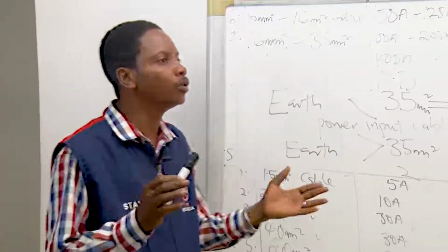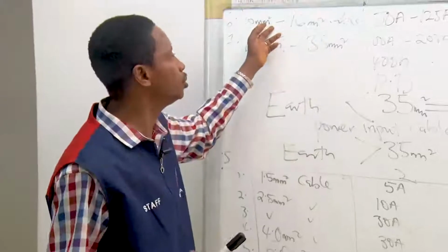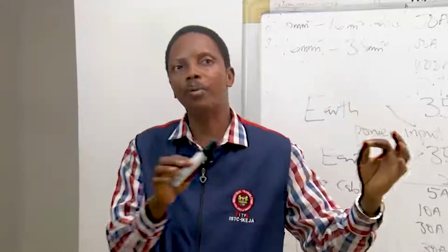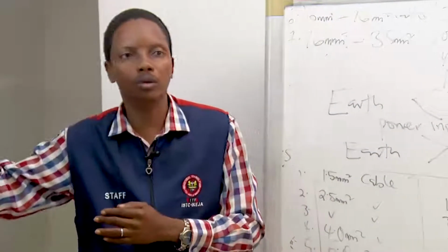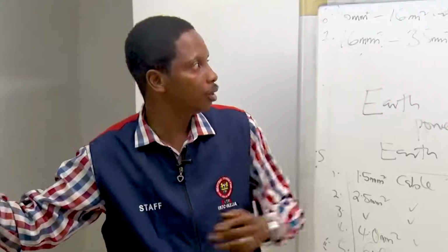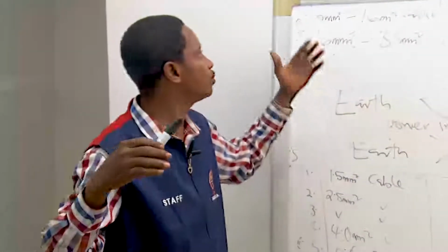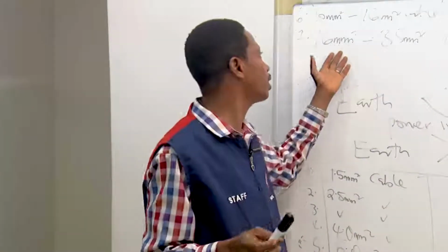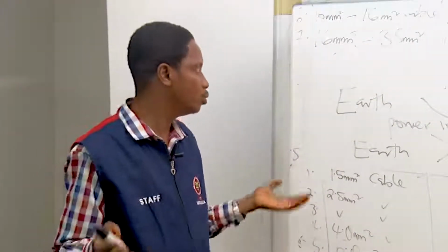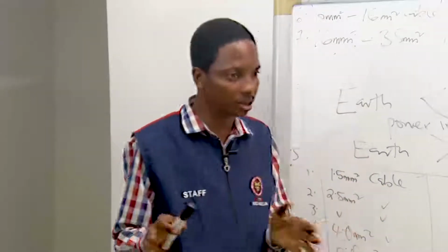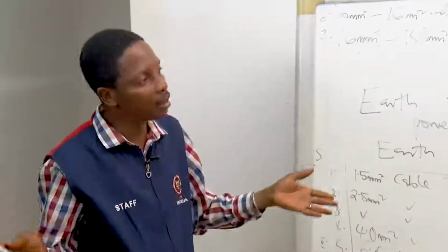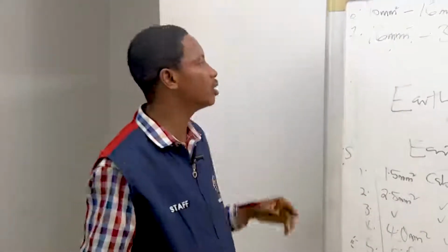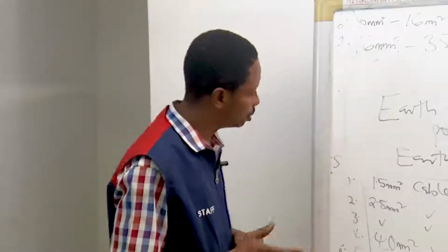And then your load cable from the main power section to your distribution board, we call it load cable. So you make use of 10 mm or 16 mm depending on the size. And then the supply cable from 16 mm to 35 mm at this level. Although we have some big factories that will extend these sizes of cable as service cable.